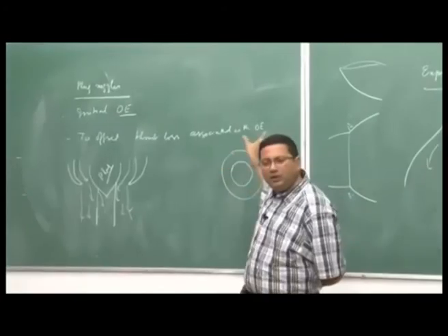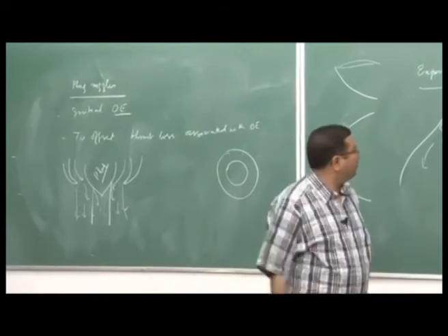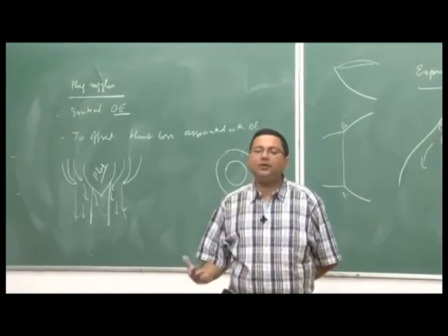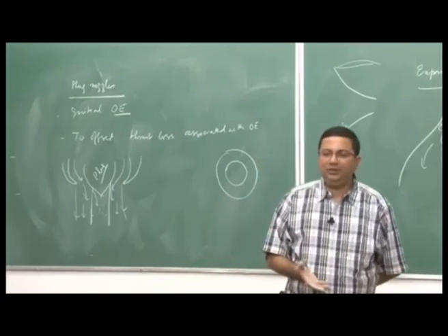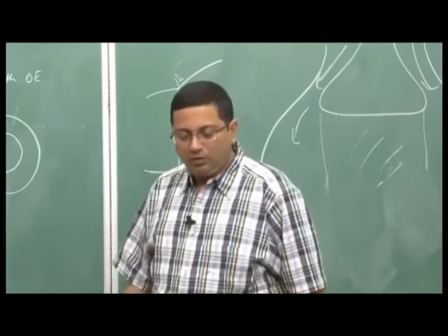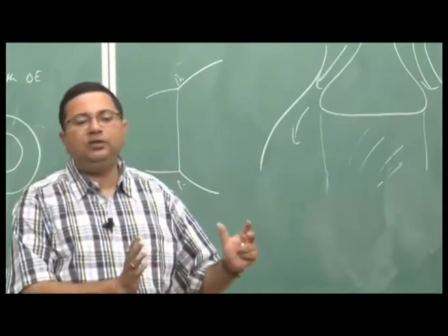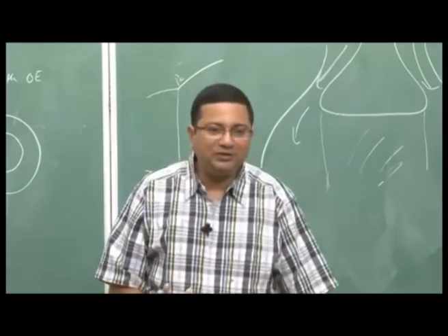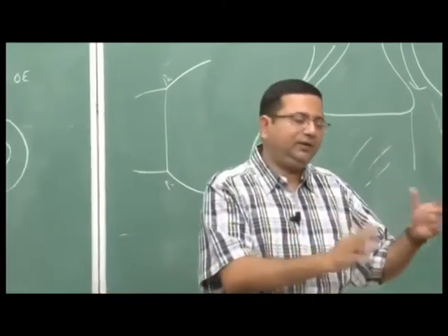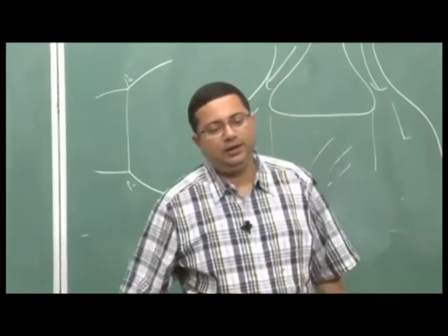then a little bit, we discussed what is a plug nozzle, what is an expansion deflection nozzle. We have also discussed how the friction or boundary layer affects the performance, we discussed how the back pressure affects the performance. So, essentially all this part was focused on the thrust coefficient maximization, right. So, the entire nozzle discussion was focused on that.